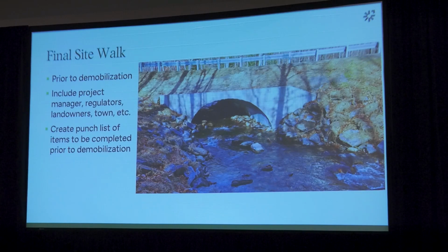So, after site restoration, we want to make sure, similarly, before the contractor demobilizes, that we have a final site walk. This is a point where we'll include the landowners, regulators, the town, anyone interested and involved in the project to come view the site while the contractor is still there, while we can still make adjustments, and create a punch list.